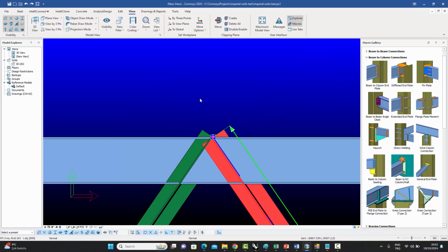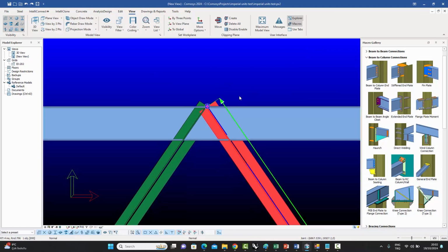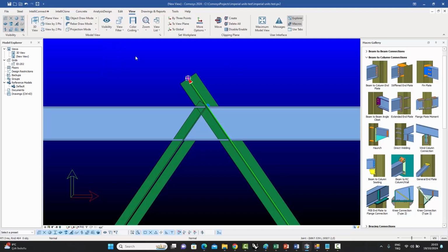That's the first thing. The second thing is that we've added handles, like I said, and the handle I want to talk about first is the three handles over here: the arrow handle, the tail handle, and the pink dot in the middle. What the arrow handle does is, if you select that and you give it a number, let's say you move it, it's going to extend the frame in the original direction by whatever amount you enter. And this is going to actually physically move the element to that point. So the node also moves to that point.